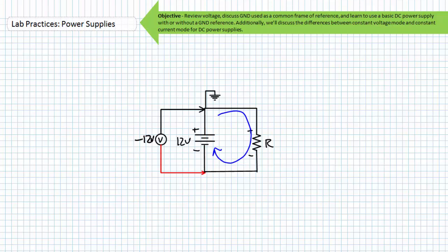This being said, it's not normally done this way. Most systems, if they include a ground reference, do so on the negative terminal of the source. Positive ground and even central ground systems exist. There's no law saying that you have to be readable, consistent, or understandable. Surely half the problems in the back of electronics textbooks are just simple circuits purposely trying to look goofy and hard to read. I am not trying to softball you when I routinely present sources on the left-hand side with a positive terminal pointed up, the negative terminal pointed down, and if I incorporate one at all, a ground reference on the negative terminal. You can do it any way you wish.